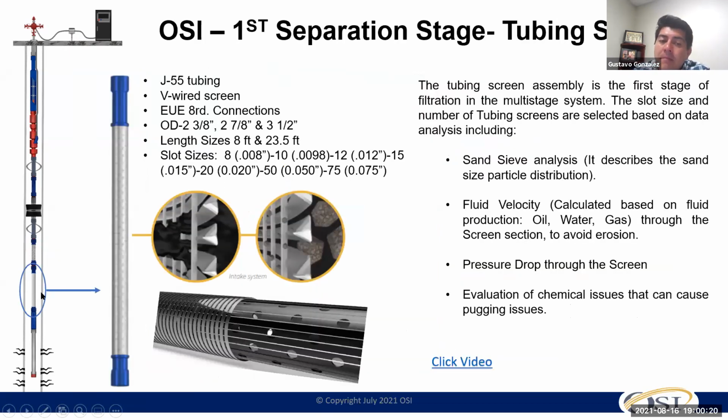One of the things to go back to with the main screen as the primary intake is that there are different slot sizes, and the common question that we always get from people is, I'm dealing with 100 mesh or 40/60 or 40/70, and they say, give me the tightest screen that you have. If we do that, as we mentioned previously, due to the volume, we're going to plug the screen because, as we saw in the photos at the beginning, the sand is more like a paste. So based on those cases, we try to talk with people about regulating instead of filtering everything at once.